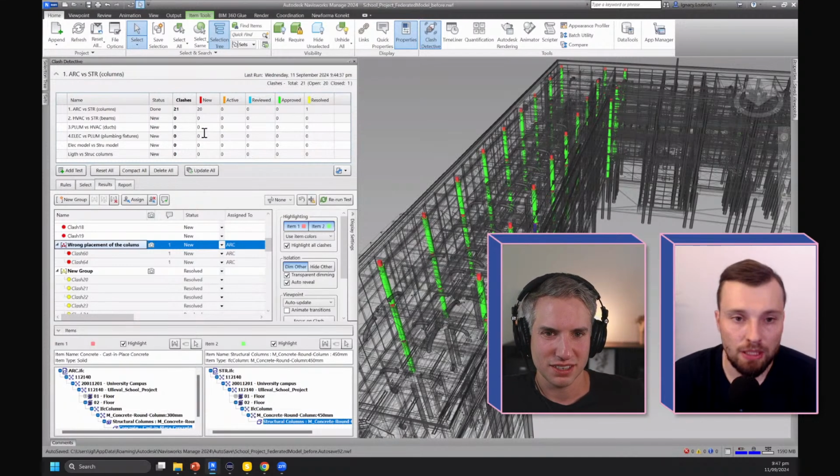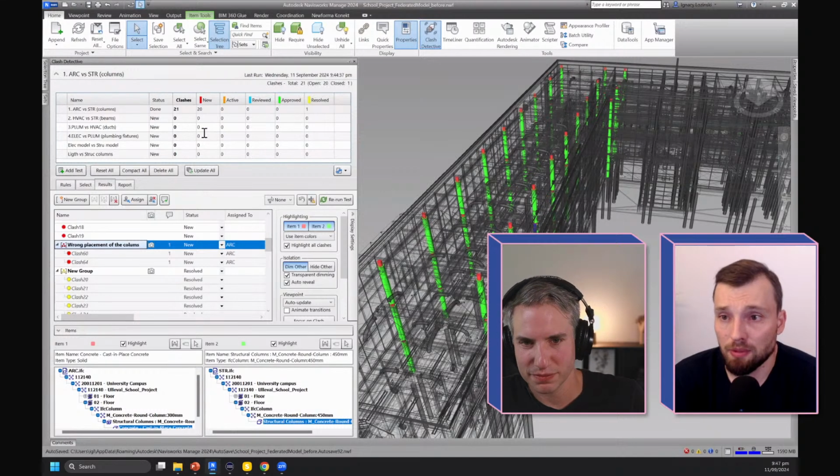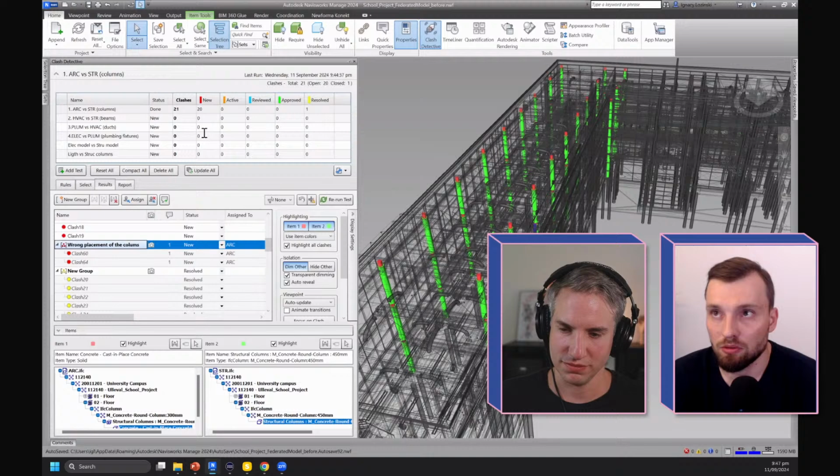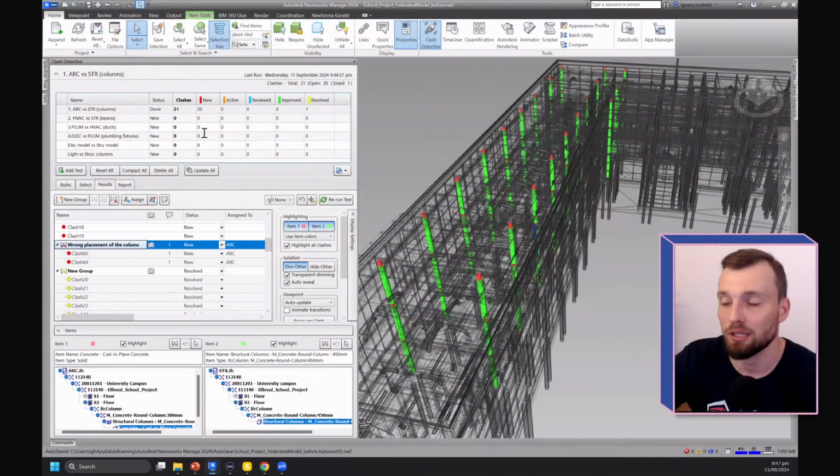Yeah, okay. Of course, we have problems with IFC files and grouping them into the right category. This is a big case, because let's say that we have doors, and doors should have the entity IFC door, but sometimes they have IFC building proxy entity, which is a general one. In more human-friendly language, it's an object, not a defined object.